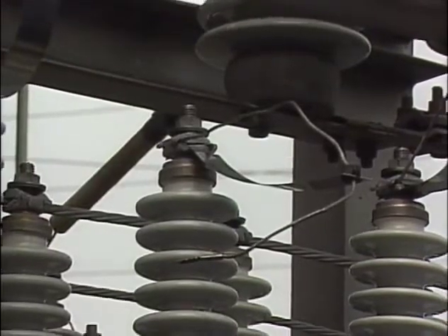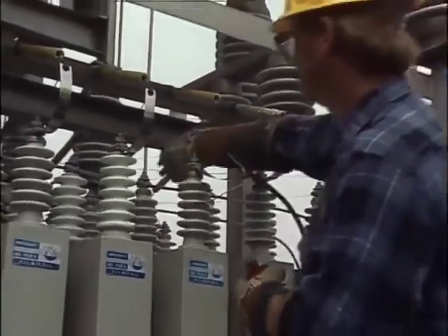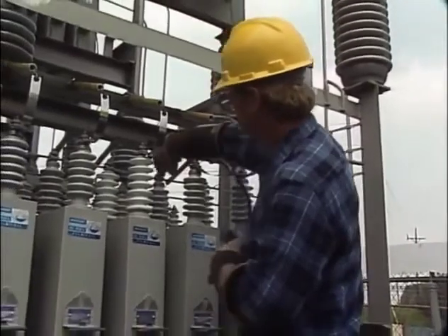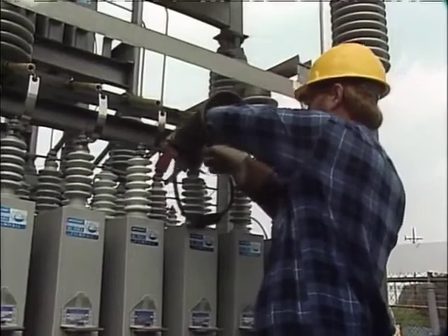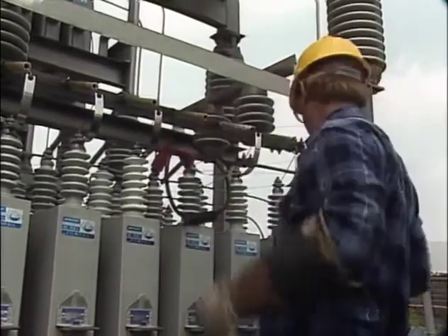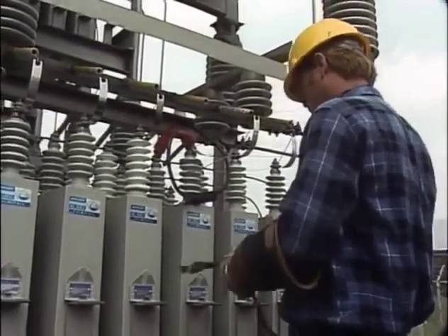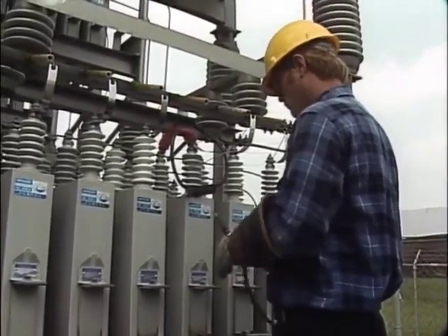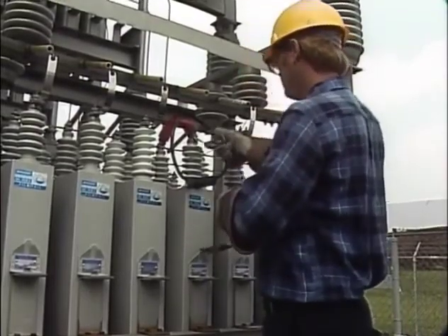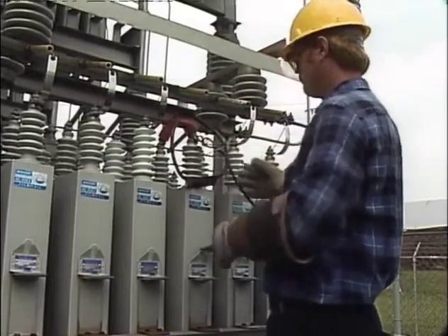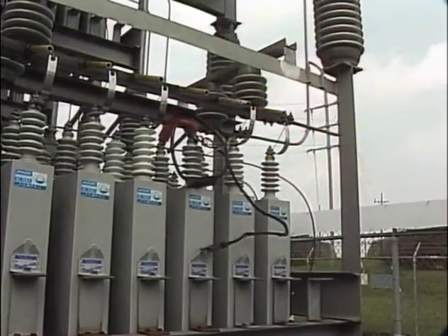Before working with a capacitor that has a blown fuse, it's very important to short the capacitor terminals together with an appropriate shorting device. The short is needed because the blown fuse disconnected the capacitor from the source bus before the bus was grounded. As a result, the capacitor may still contain a charge. As an added precaution, a short should be applied from the capacitor tank to the shorted terminals. This protects against a discharge resulting from an open inside the capacitor.